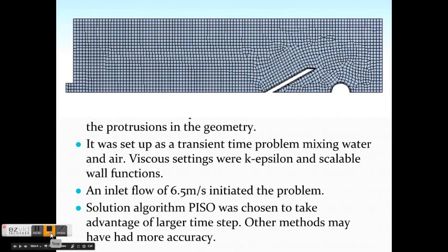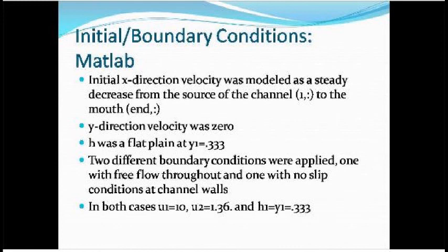A problem between Fluent and MATLAB that limits comparisons was that the flow velocity had to be less in Fluent in order to simulate the desired behavior. Also, the waves failed to be modeled in 3 dimensions, and only the xz plane modeled the desired behavior.